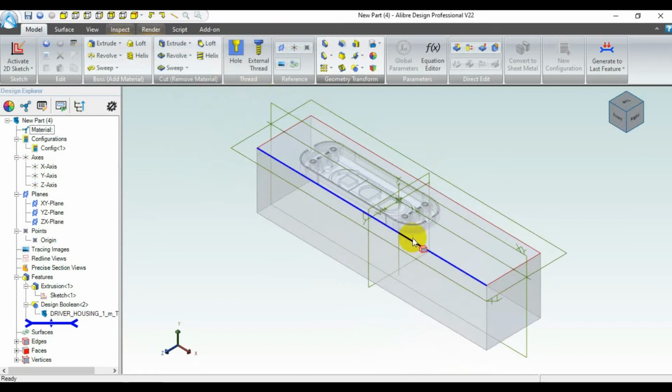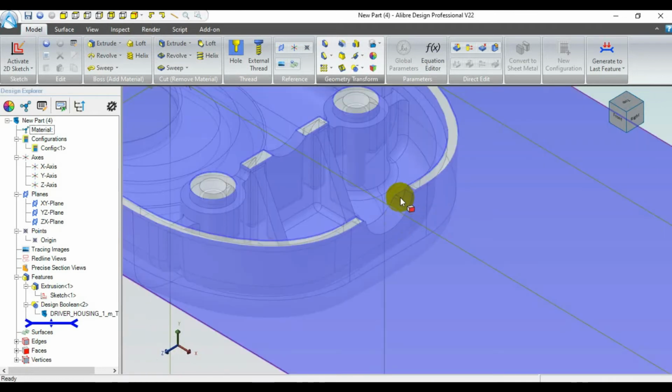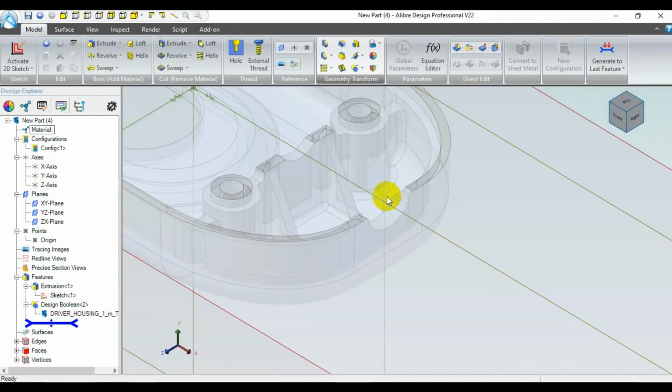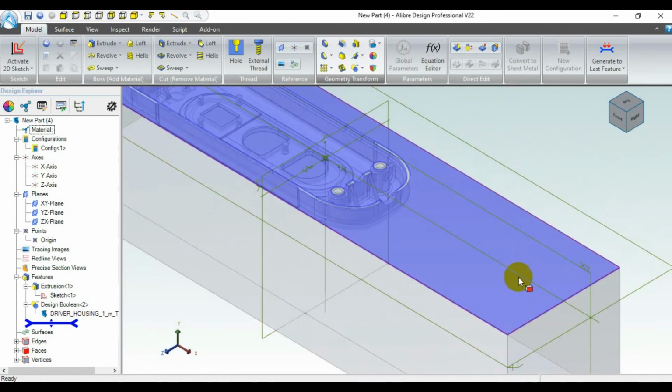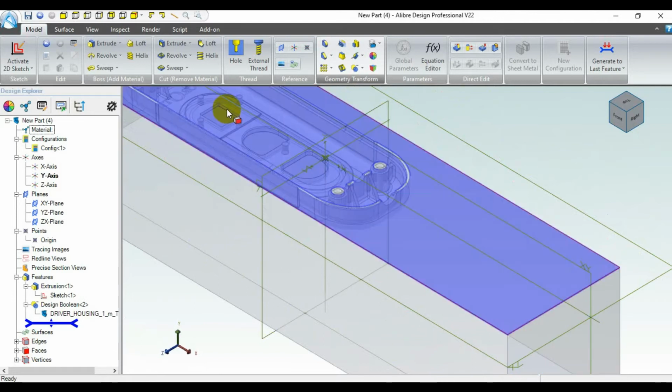Now in injection molding, and I'm a tool maker by trade, it's a good idea to create a nice simple shut face that basically makes it easier to work around here. So what I'm going to do is create a cutout that runs all the way through here to do this tunnel, and we'll ignore what happens in the middle here.